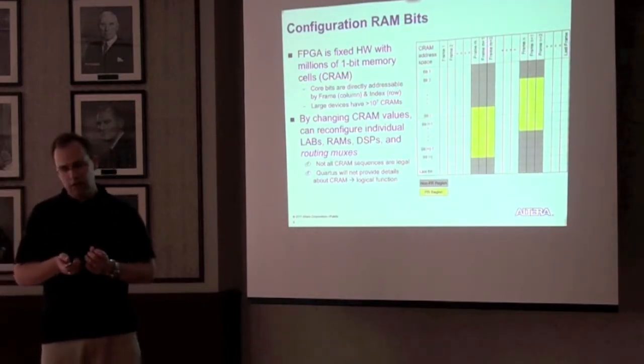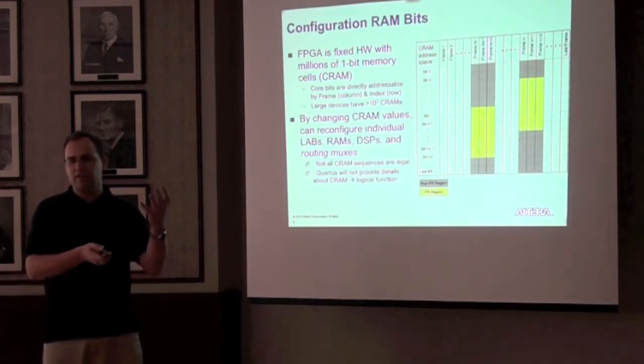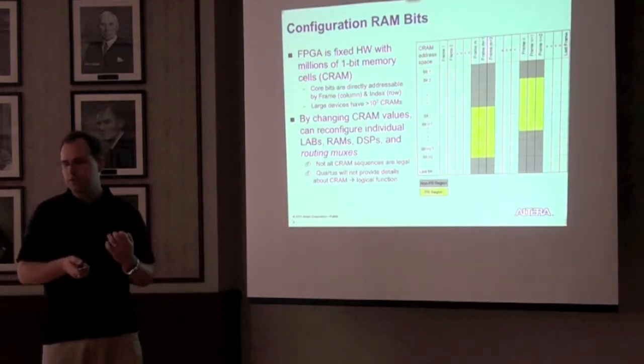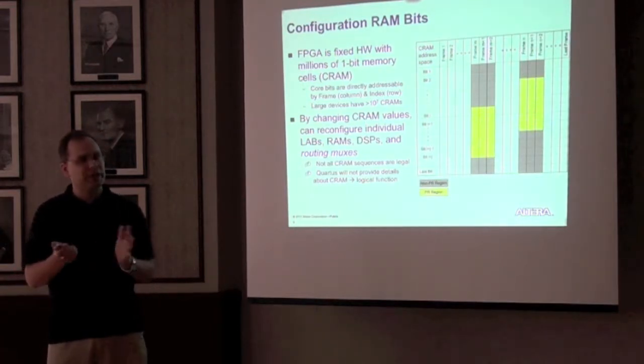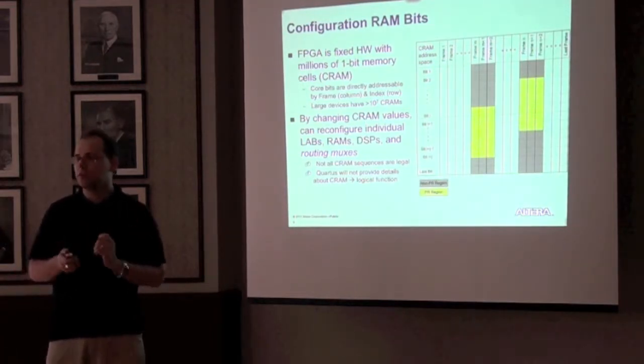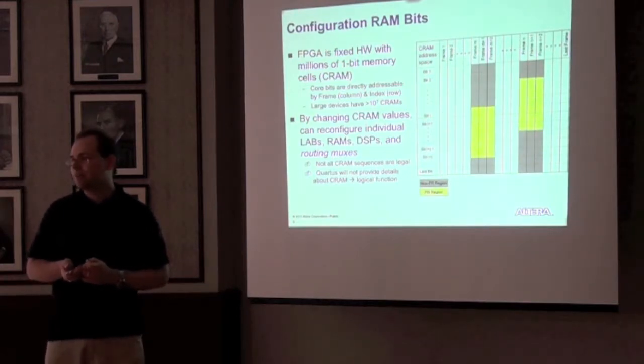As you can imagine, not all CRAM sequences are legal. If I have a bunch of tri-stated drivers, or multiple drivers, if I set them all to 1, you can have a short, so we have to be careful to prevent illegal sequences, and I'll go into a little bit more about these details later.